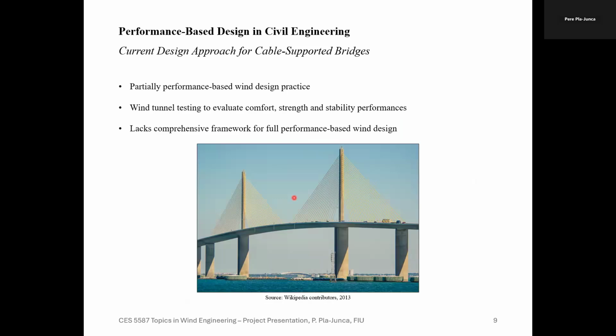In the field of cable-supported bridges, where we stand is that the current design practice is actually partially performance-based. Its cornerstone is wind tunnel testing, which is used to evaluate comfort, strength, and stability performances. However, overall, there's a lack of a comprehensive framework for full performance-based wind design. So currently, it is considered prescriptive, not performance-based.